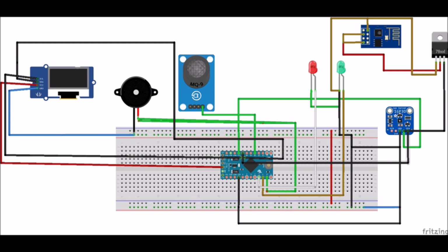It is built around the Arduino Pro Mini board. The MQ2 gas sensor module was connected to analog pin 1 of the Arduino Pro Mini board, while the MQ135 was connected to analog pin 2. The power rails for these gas sensor modules were connected to the 5 volts and ground pins accordingly. A buzzer is added to the design for alert beep. We used the LM7805 to denote the supply of 5 volts to the circuitry.